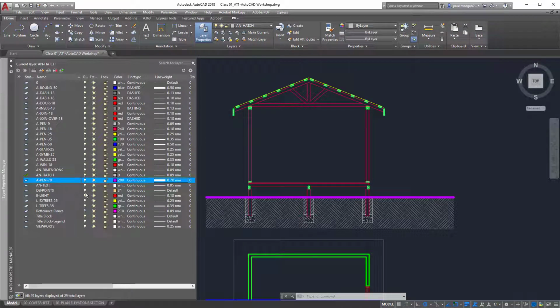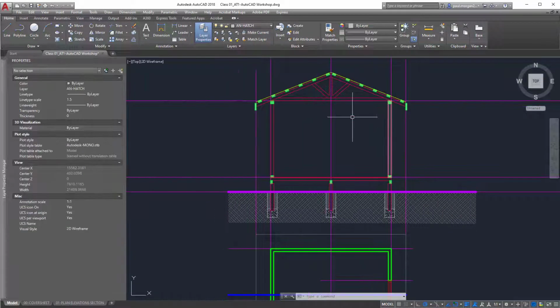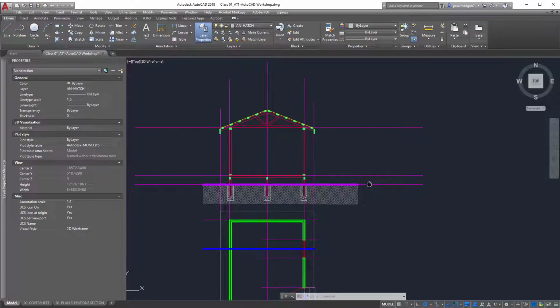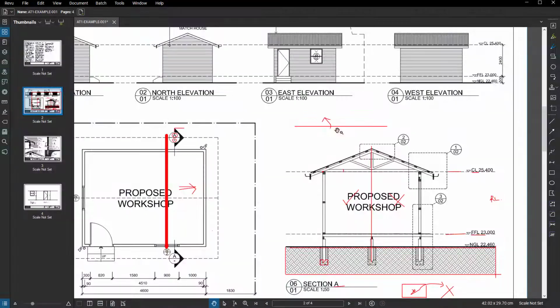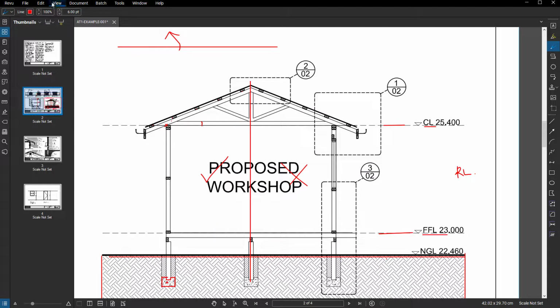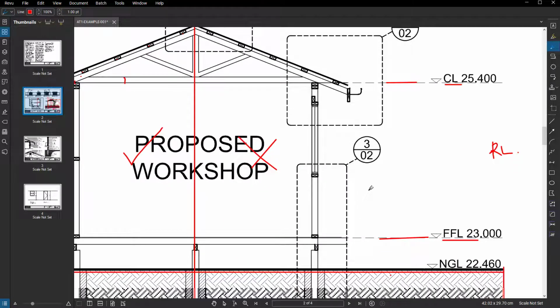The last thing to do is to go back to my reference planes and think about where we're going to have the window and how that's going to work, because that's going to carry on to the elevations. So what I'll do is I'm going to go back to the drawing. Now, typically, we dimension things from the finished floor line, and there are pretty typical heights for certain heights of ceiling. As an example, this is a 2.4 ceiling. So doors and windows generally sit, the head of them, generally sit at 2.1 meters above the finished floor level. So we're going to take this ground line and offset it 2.1 meters. That gives us this head height for the window.